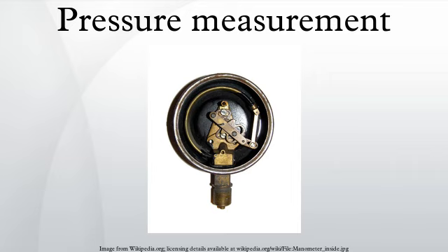0.1 millipascals is the lowest direct measurement of pressure that is possible with current technology. Other vacuum gauges can measure lower pressures, but only indirectly by measurement of other pressure-dependent properties. These indirect measurements must be calibrated to SI units via a direct measurement, most commonly a McLeod gauge.